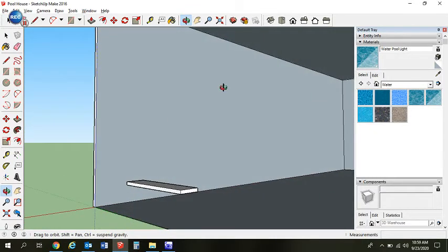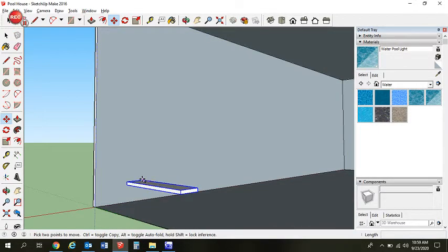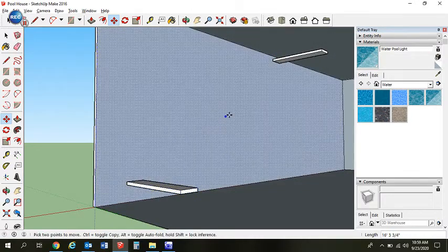Orbit, and I'm going to copy this. Now the instructions say to use 9 steps in between, but I found that's pretty wide steps. You have to be a big stepper and not fall through the holes. So next, when we copy, we hit our move tool, hit control on your keyboard, and you get that little plus symbol next to it, and that means you're copying, it's not moving it. And then what we're going to do is place it on the face close to the step. Now if you didn't click on it right where the step meets the wall, you're going to have steps going into the wall. Now don't type anything else.